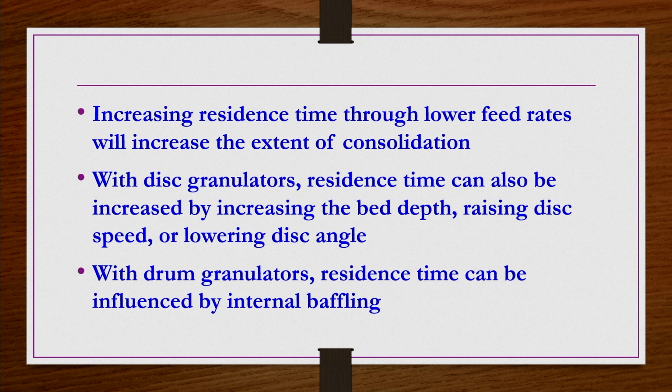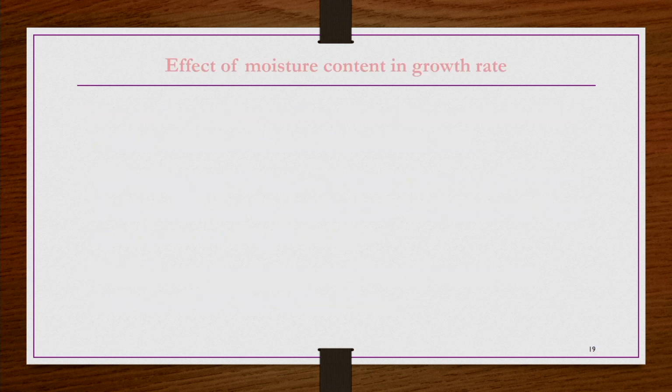Baffles are like those we have in mixers or continuous mixing equipment where reaction may also take place. In general, to enhance mixing we have baffles, and such baffles may be arranged inside the drum granulator. When you have these baffles in the drum granulators, the residence time will again be increased.